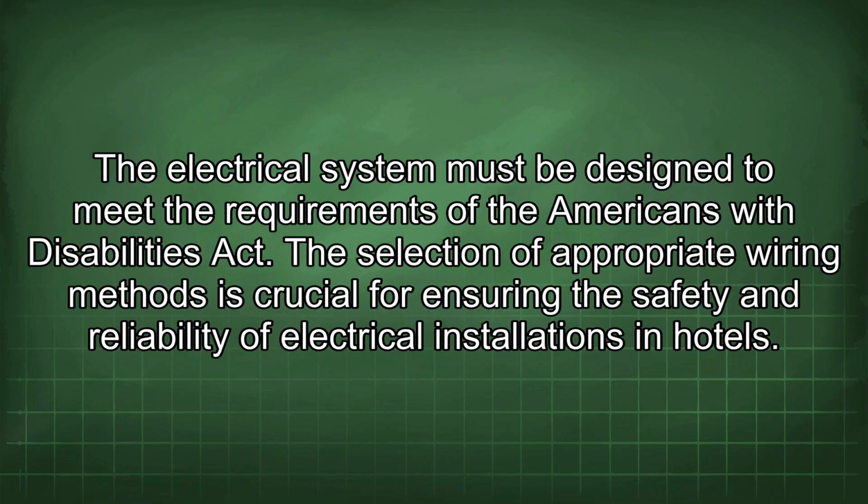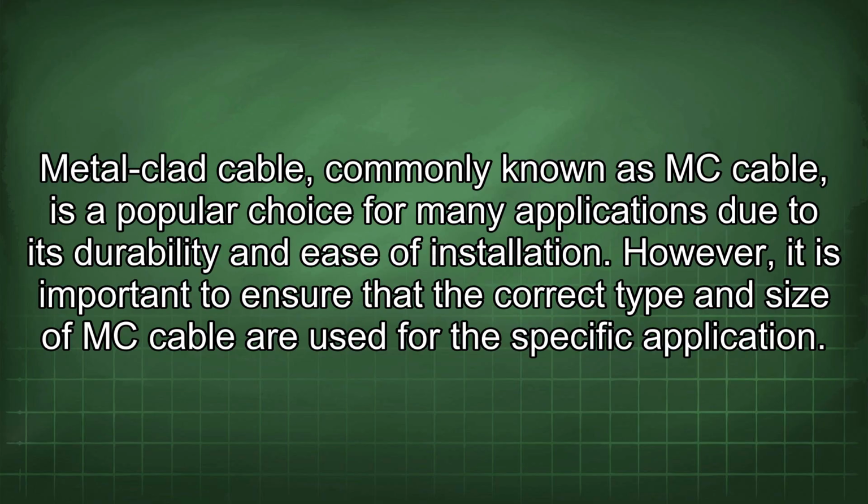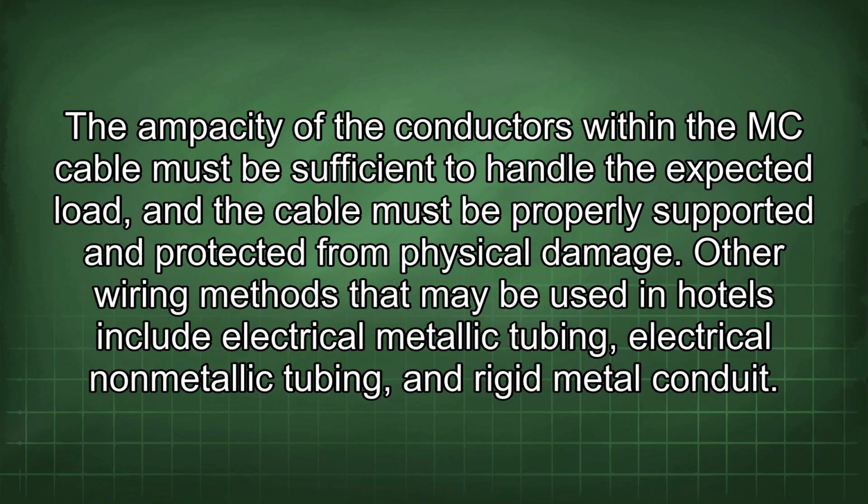The selection of appropriate wiring methods is crucial for ensuring the safety and reliability of electrical installations in hotels. Metal-clad cable, commonly known as MC cable, is a popular choice for many applications due to its durability and ease of installation. However, it is important to ensure that the correct type and size of MC cable are used for the specific application. The ampacity of the conductors within the MC cable must be sufficient to handle the expected load, and the cable must be properly supported and protected from physical damage.